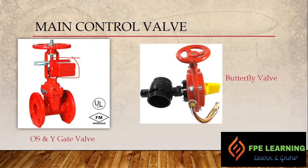Now how are you going to identify whether the valve is open or closed, right? Look at this system, right? If the rod is outside like this, up to this point, it means the valve is open. At this moment this valve is closed because this system is totally inside, right? If this rod, this system, we call it the system, comes up to this point, it means the valve is open. At this moment it is closed. And if you are closing the valve, you are not allowed to close it in less than 5 seconds because of the problem with water hammer.